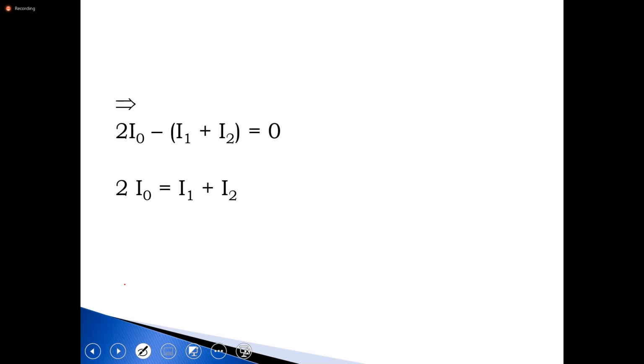Now, what did we say about zero sequence currents last week? They cannot flow unless there is a path to ground. Absolutely. Now, is there a path to ground here? No, because you only have the two phases coming together. There is no connection with Earth.